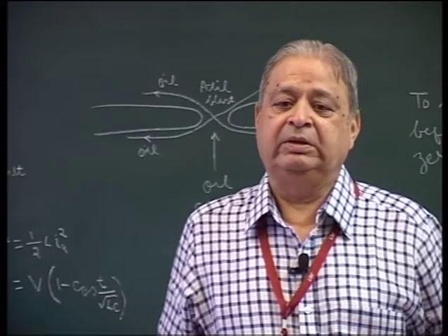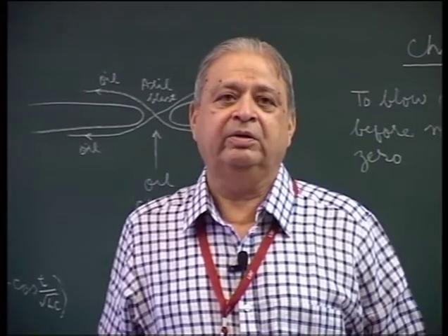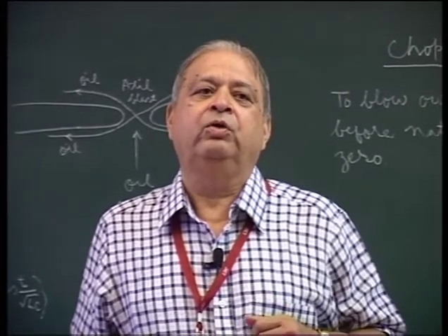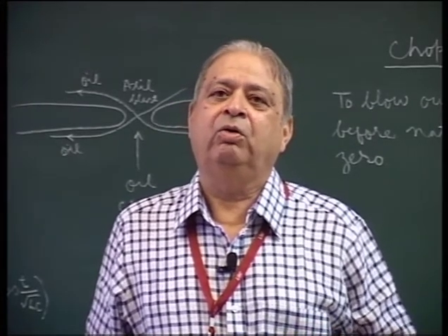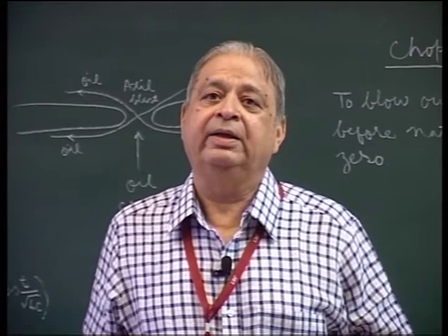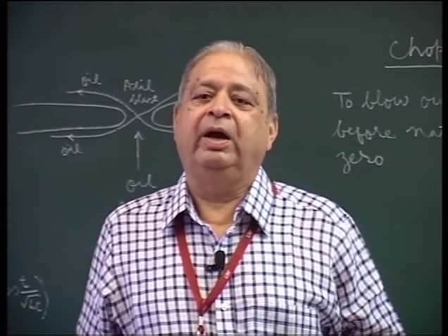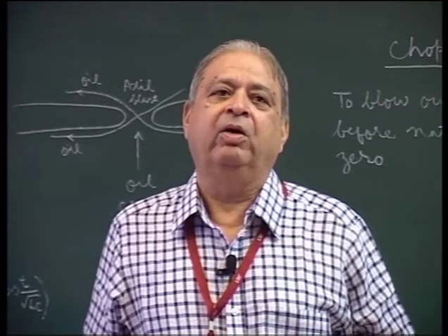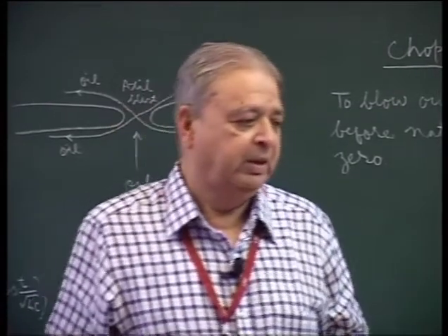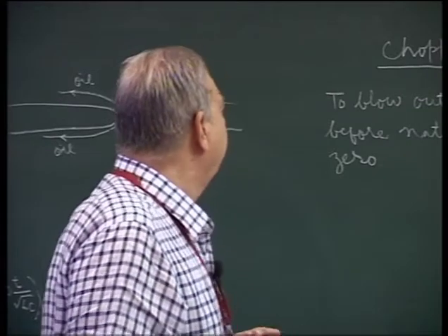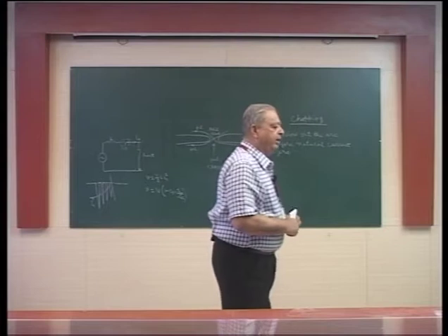Whereas in certain circuit breakers, like in air blast circuit breakers, this force to blow out the arc is a constant force, whether the current is low or high. In both cases it is the same force, and there is a greater possibility of the occurrence of current chopping. Now another thing to weaken the arc is to go by resistance switching.